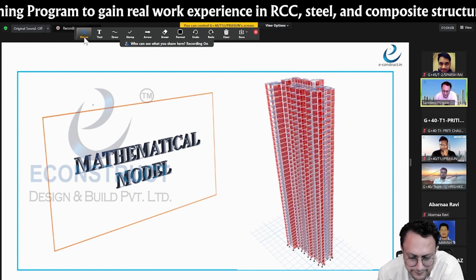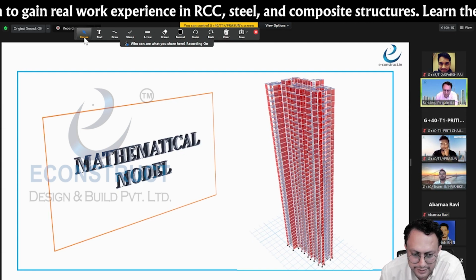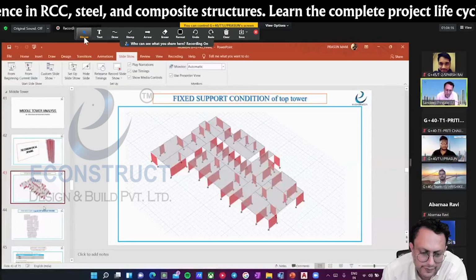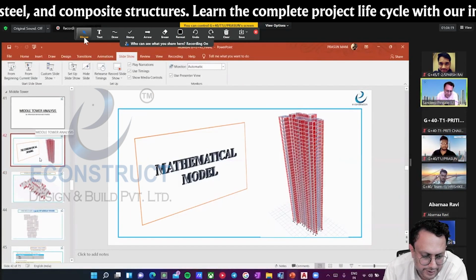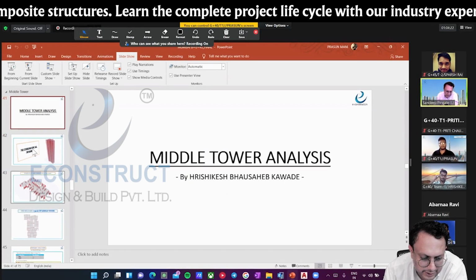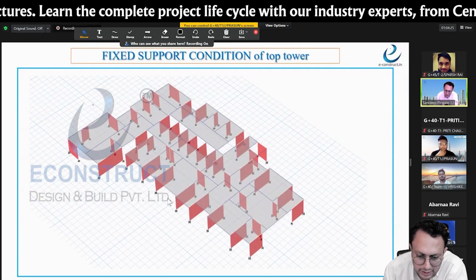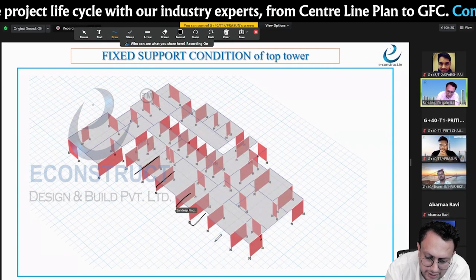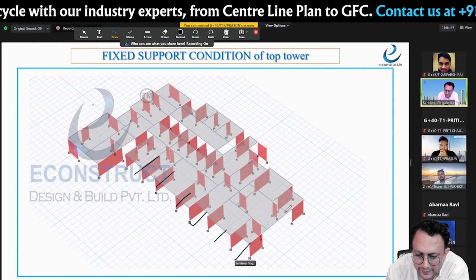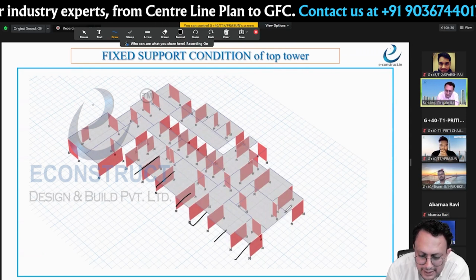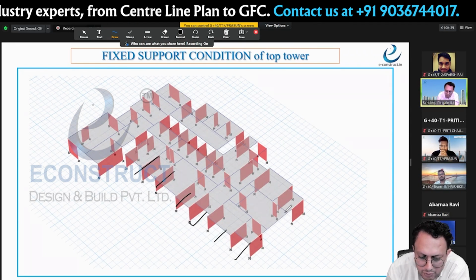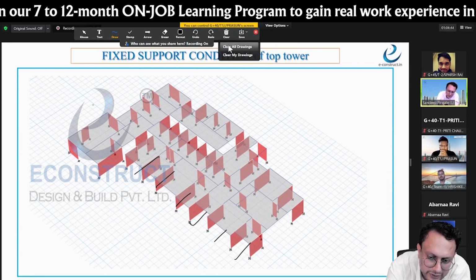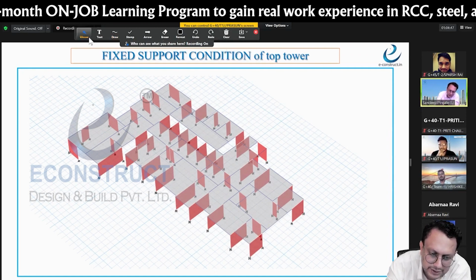Next slide, please. Yes, this one. So you have already given a good number of walls in this direction. See here, these are all the walls that are going to resist anyway. So I don't think there is an opportunity to give more walls than what you have given. Check the wind load calculation. The gust factor, I'm not sure that is right.